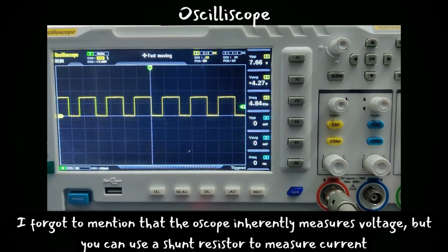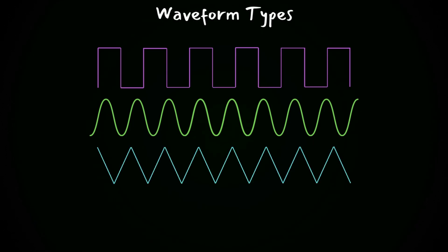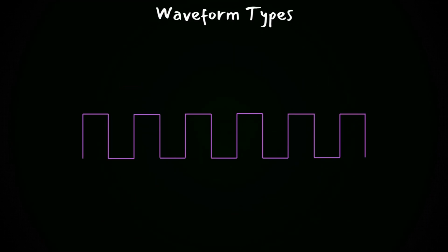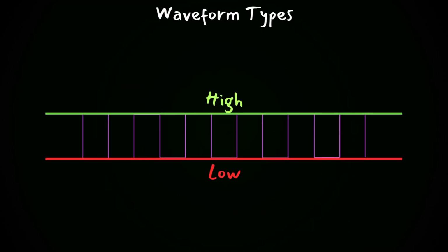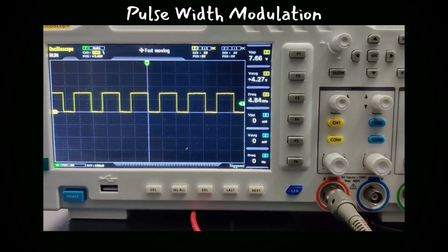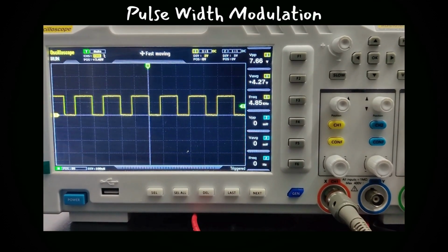As a side note, there are multiple waveform types. Most common are square, sine, triangle, and complex. Each has their own specific use, but I'm going to be focusing on a square wave, since square waves only have two states, high and low, and are perfect for PWM. But before I can create the square wave, I need to explain key parts of a waveform to you.